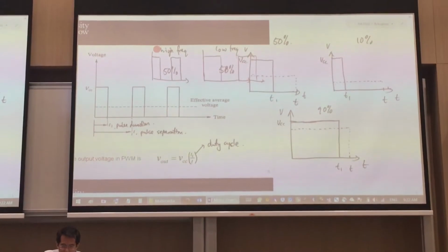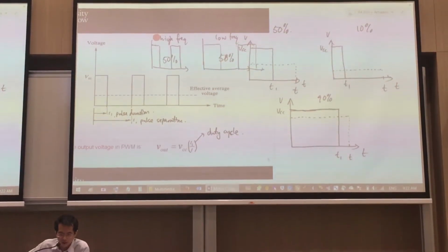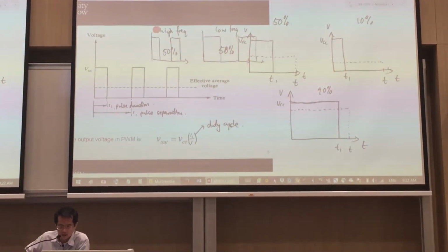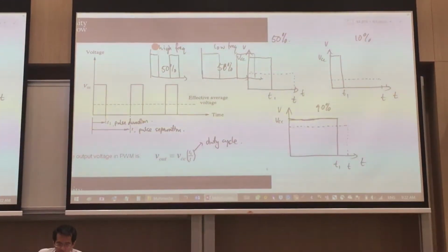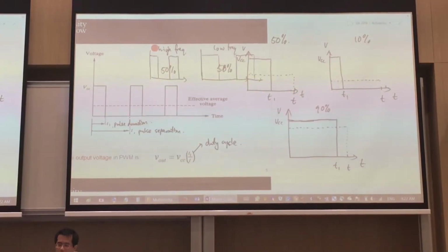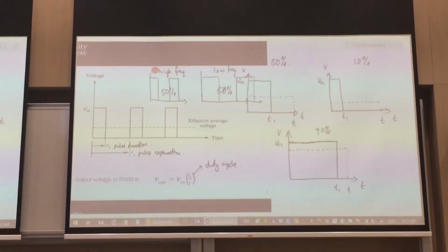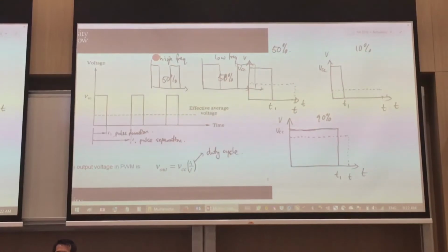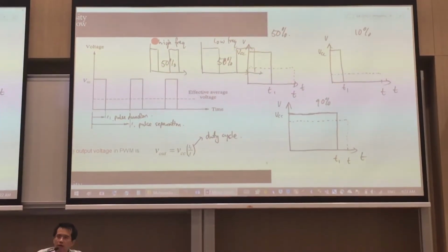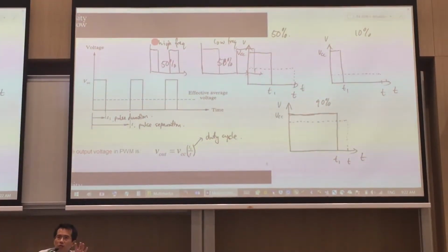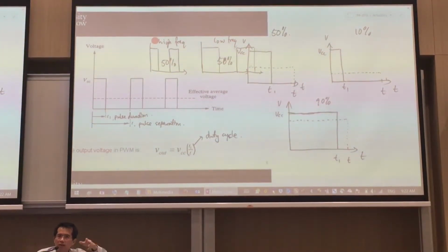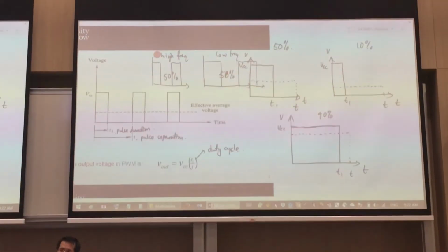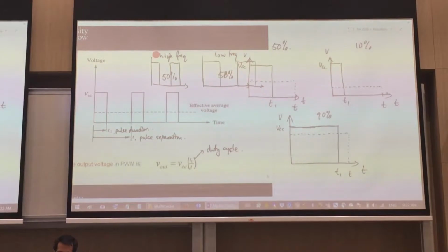Then how high a pulse rate can we go? How high a frequency? Usually it is about 2 to 20 kilohertz. That's the PWM signal. And you will want to have this pulsing of PWM avoiding the natural frequency of your motor. Now your motor, as you operate it, will actually resonate at a certain frequency. And this frequency normally is in the lower frequency.